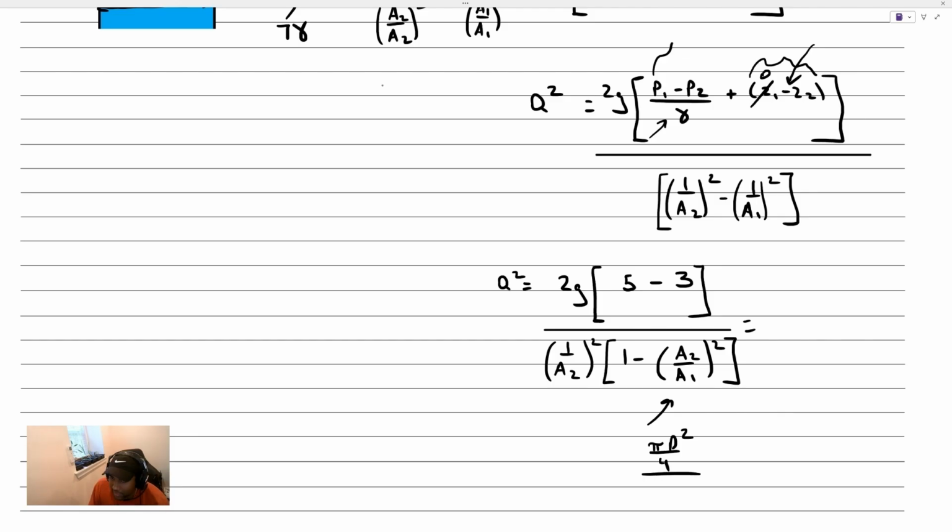And A1 had a 50% larger diameter, so it would be like pi times 1.5d squared over 4. Some of these pi's and 4's cancel out. So essentially, a ratio of areas, A2 to A1, is equal to a ratio of diameters squared, where the d's cancel out, and I get a 1 over 1.5 squared.